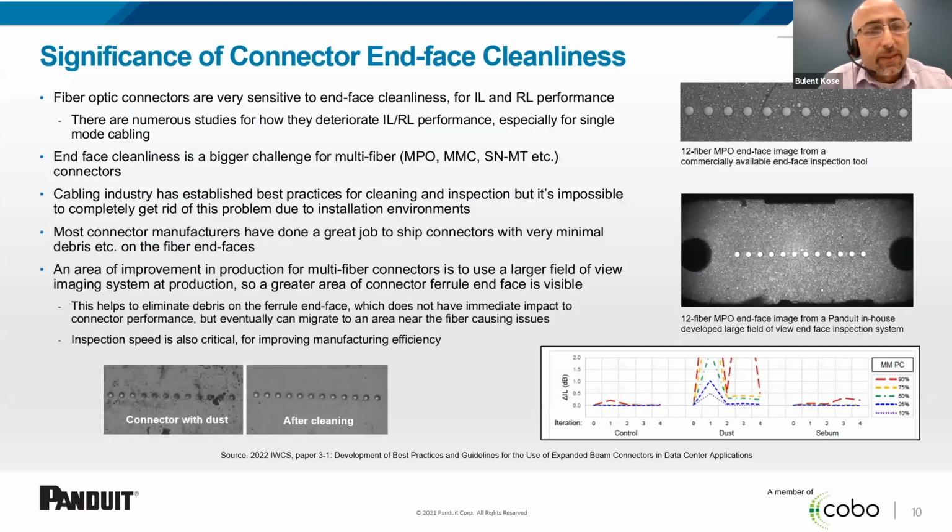Okay, so now I wanted to talk about some of the installation issues for multi-fiber, high-density connectors, starting with the end-face cleanliness problem. Fiber optic connectors are very sensitive to end-face cleanliness, obviously, which causes insertion loss and return loss performance issues, and especially for single mode fibers, this is even worse. And this is a bigger problem for multi-fiber connectors.